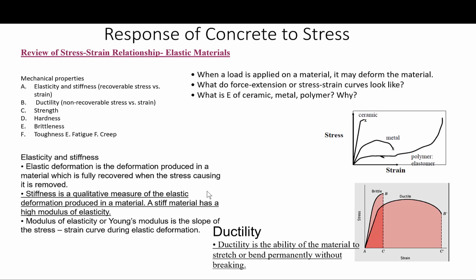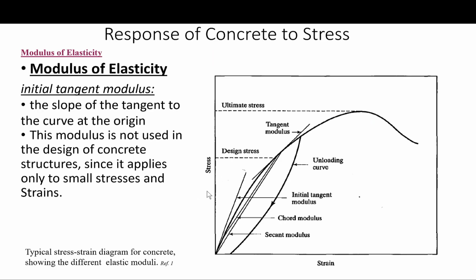And again, we will reintroduce you to the various terminology of mechanics of materials, what the terms are and what they mean, before we get into the concrete. Then we will study and explain, because as I said, concrete is not a homogeneous material, so determining, for example, the modulus of elasticity is not a straightforward approach.